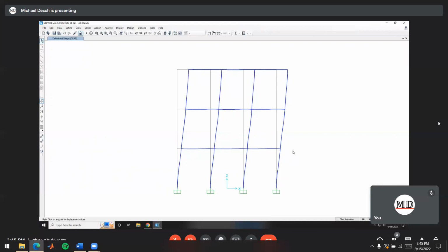So when we do that, we can pick any point on this floor here, and it'll give us our story displacement value. And we want one for each floor to see how much each of our floors is going to move, basically. That makes sense? Usually I pick them on the right-hand side here, but any of them should be fine. And when we're grading the lab reports, I make sure to accept the whole range. So it doesn't matter which one you pick, but I usually prefer to take them on the left-hand side here. That's just my preference, though. Or right-hand, geez. Okay, any questions on that?